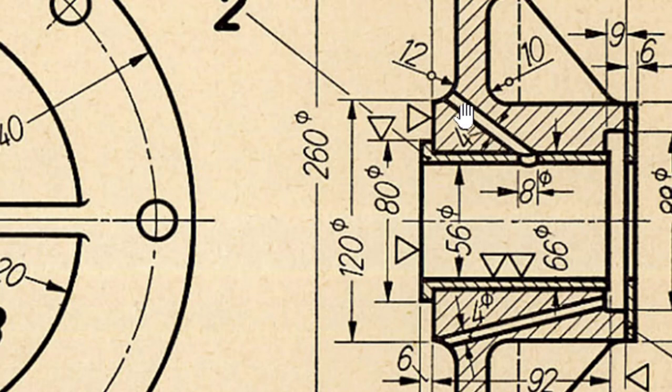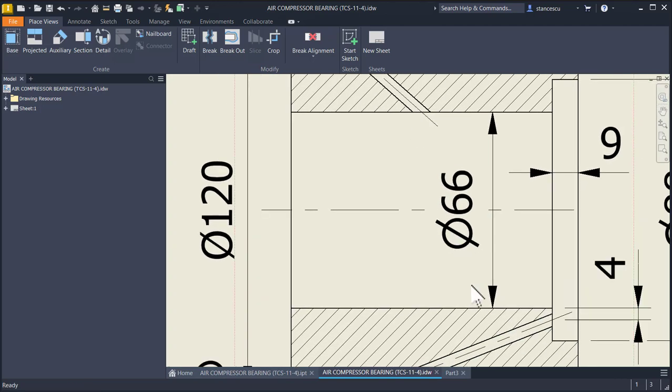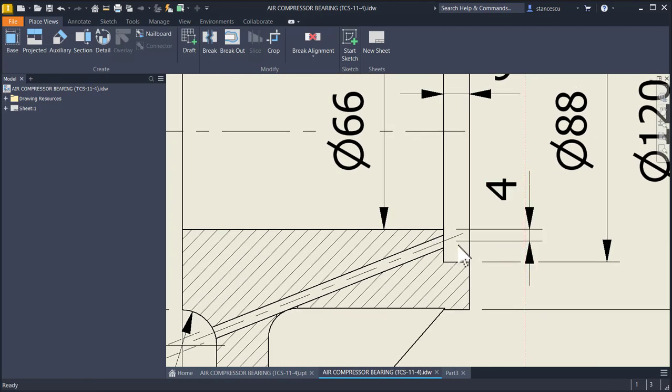We focus on this line. It has no position, horizontal, and I think half of this is very good. Here we have another hole, and I place the first point also in the center of this arc, because I repeat, this is not hollow, this is material. You will see when we create this. Good. I placed here a dimension of 4 millimeters from this point to this line.